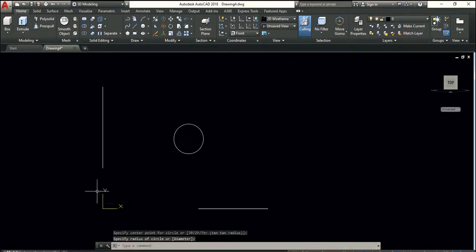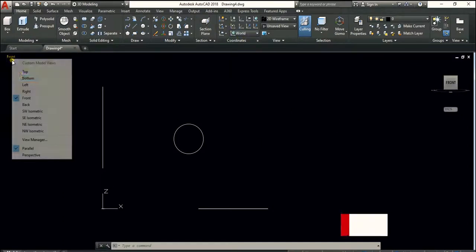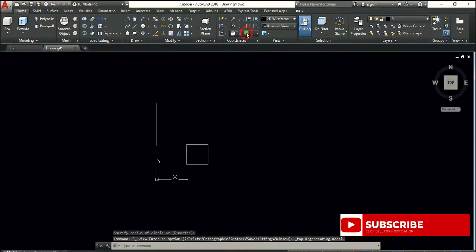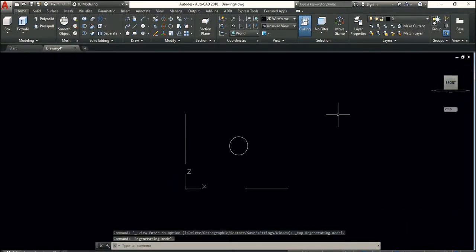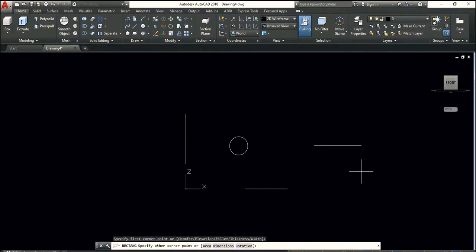But you notice this is constant because it's just assuming this has now been set to your XY plane. Like I said earlier, when you're creating any 2D shapes, they are usually created in your XY plane. So this is forcing the front view to your XY plane. That is why this is handy and not that. Okay, if I go back to my wall and take this back to my top, so this is the wall now. If I go to my front view and try to create anything, can you see I can't create any front view, even though the view cube is telling me front view. I'm constrained to the world control.